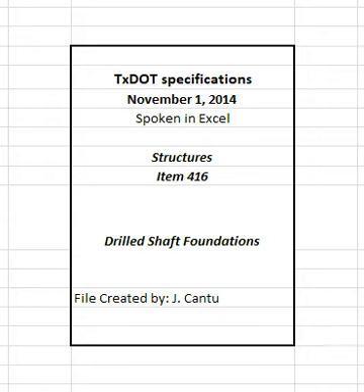Details of overall construction operation sequence and the sequence of shaft construction in bents or groups. Details of shaft excavation methods. When the use of slurry is anticipated, details of the slurry mix design and its suitability for the subsurface conditions at the construction site, mixing and storage methods, maintenance methods, and disposal procedures.